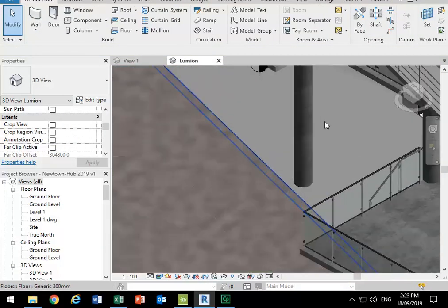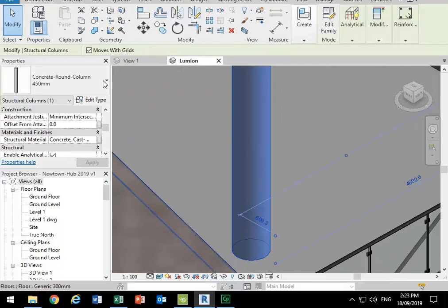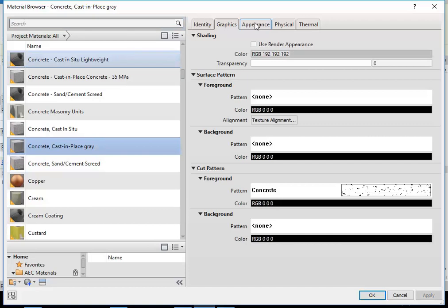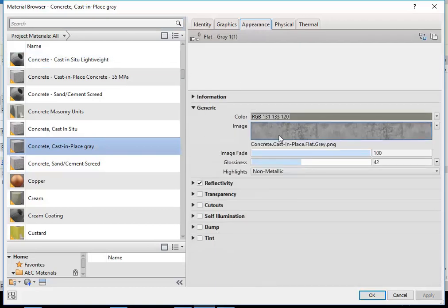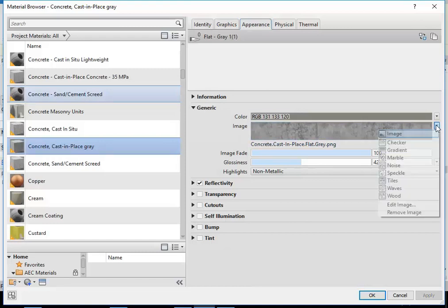And maybe it's a good chance, just while we're finishing up there, to go over all those texture-related settings. There's too much to go through everything because you've got just so many options in Revit with the different material types. But if I click on the little down arrow there, you've got these other presets. They can be extremely useful, particularly tiles and gradient and so on.